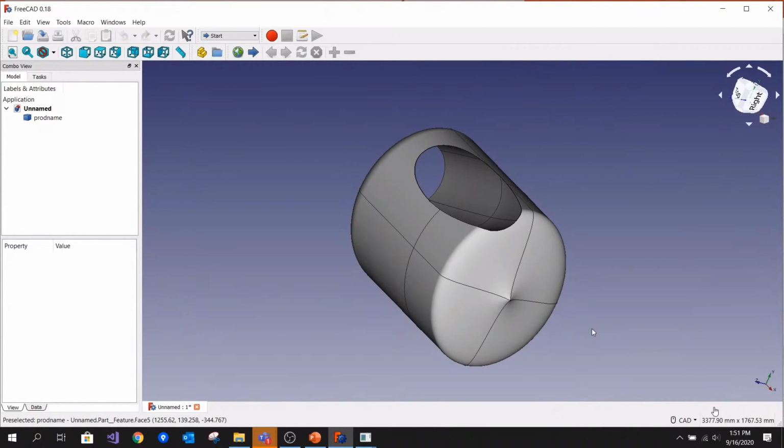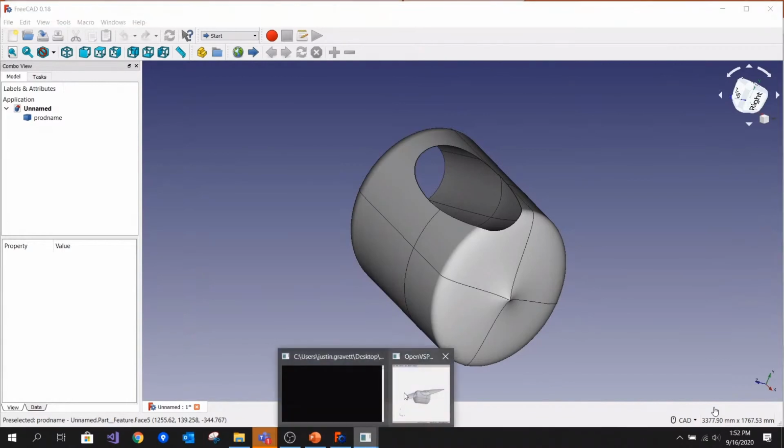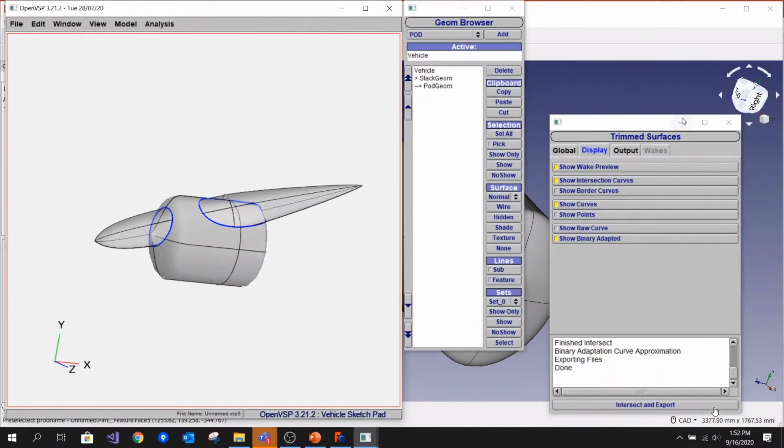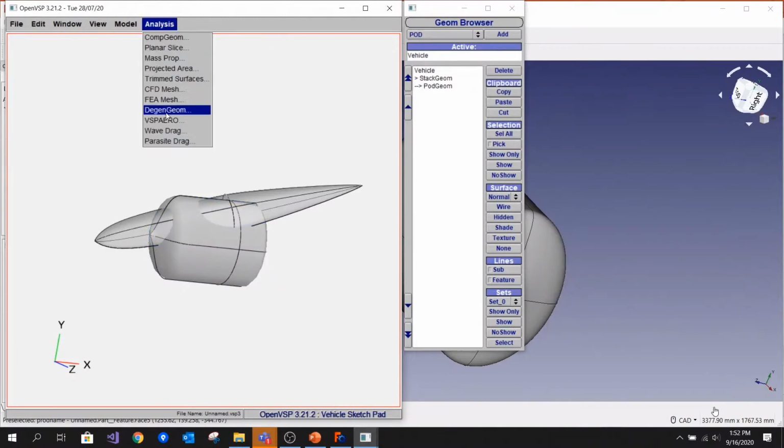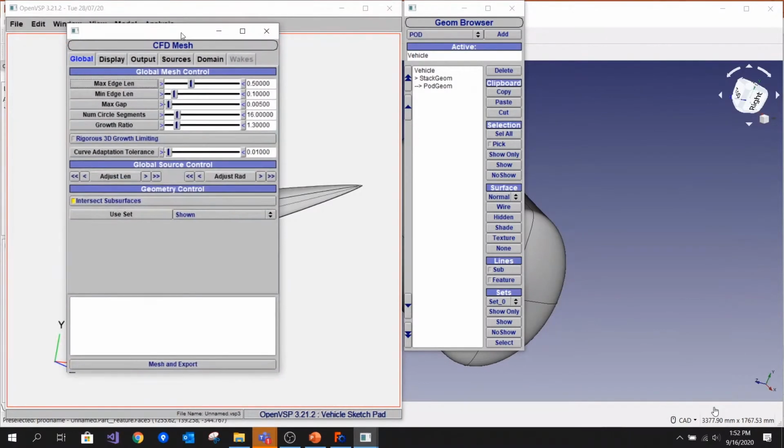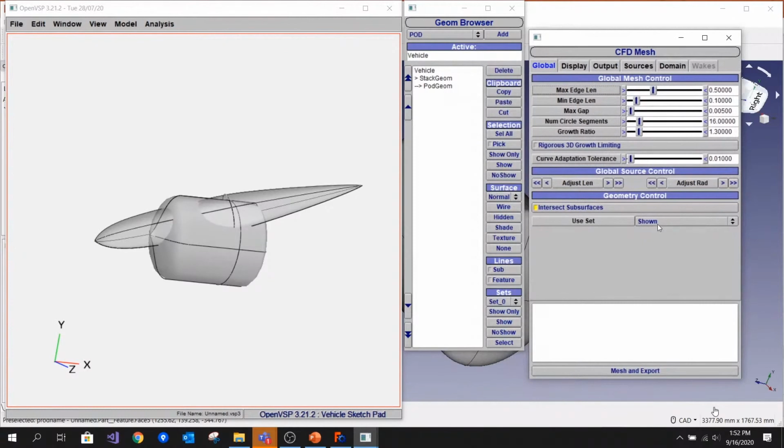When you trim a surface, you now need to generate a visualization of that trimmed surface, and VSP doesn't have that capability right now. So as Justin said, there's some ways. We're looking at some ways to visualize which component's the negative component. Justin, would you go in and run CFD mesh on that? Yeah, of course. Brandon mentioned in the chat, CFD mesh also obeys negative components.